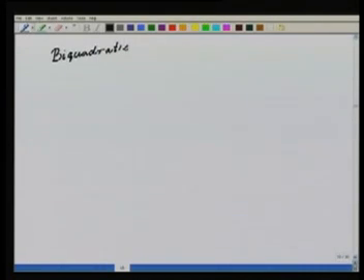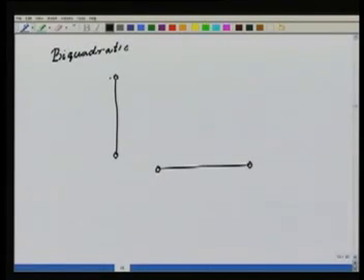So here, as we had done earlier, this is my psi edge, this is my eta edge. On these edges I'll add these additional nodes on the edge, which is at the mid side, and I'll define these 1D functions on the edge, which is very easy to define. 1D quadratic functions.